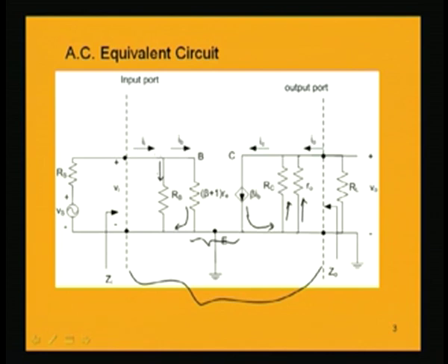The input current is Ii; one part goes through this resistance Rb and the other part through the resistance (beta plus 1) Re. So, what is Ib? These two parallel paths are there, so current division is taking place: Ii into Rb divided by Rb plus (beta plus 1) Re gives us the value of Ib.